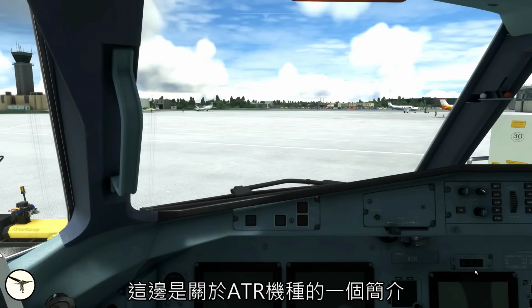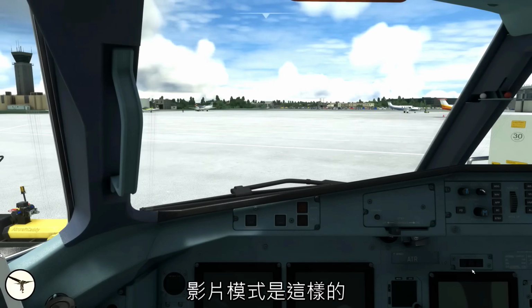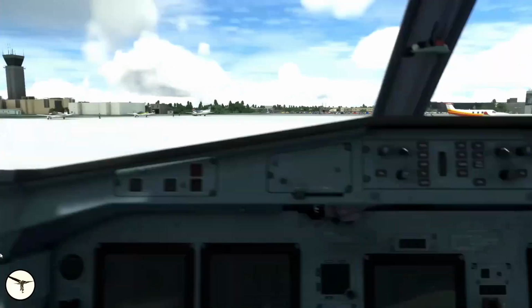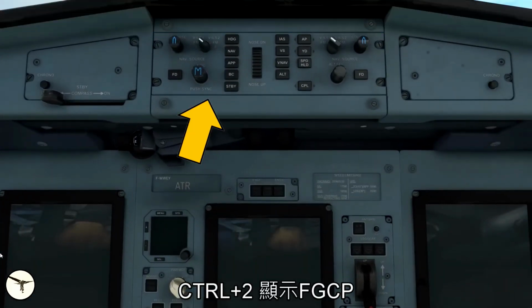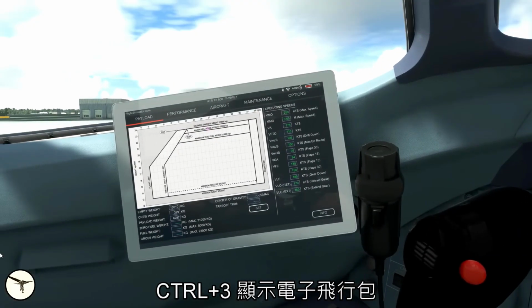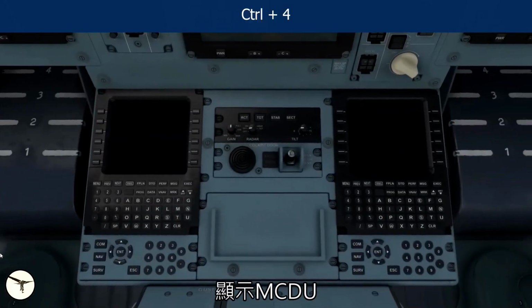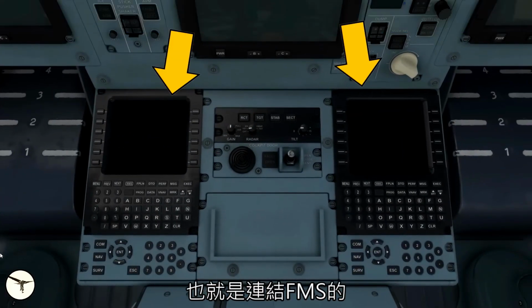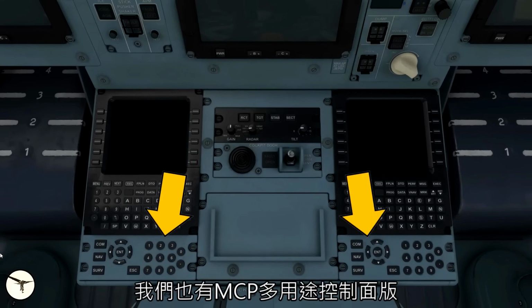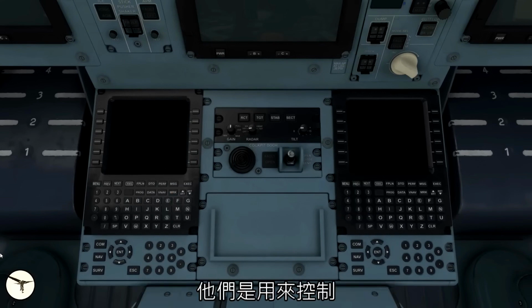Here is a quick introduction to Asobo's ATR model. The video modes are as following. Control 1 shows the instruments in front of the captain. Control 2 shows the FGCP, Flight Guidance Control Panel, or Autopilot Panel. Control 3 shows the electronic flight bag. Control 4 shows the MCDU, which is used to communicate with the FMS. We also have the MCP, Multipurpose Control Panel, which is used to control the radio and navigation equipment.